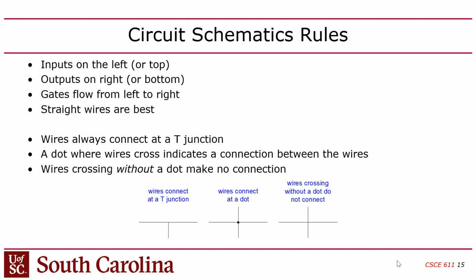Remember that when you have connections like this, there are basically 3 points on the connection. You can only have one driver for that net, that wire. So only one logic circuit, which could be a module that you instanced, or some behavior that you put in, like an assign statement, can put a logic value on this wire. Because there are 3 points, probably one thing is driving it, and then there are 2 things going to inputs on other parts of your diagram. Does that make sense? Okay, so just keep that in mind.